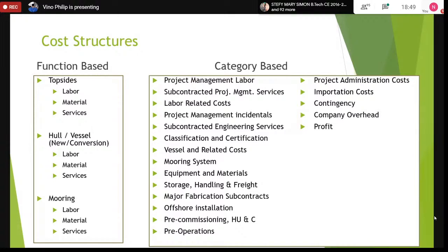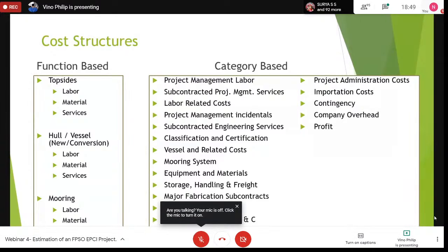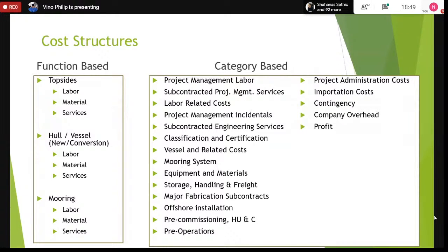So we do an evaluation of the hull strength properties and fatigue analysis of the hull, and we have to calculate which spots are tender for the vessel body itself, which are the most exposed to fatigue. And those points most likely will be the attachment point for the mooring lines. We have to go there and do further investigations every 10 years to do a continuous evaluation of the vessel to make sure it is seaworthy. And those are risk-based evaluation studies.